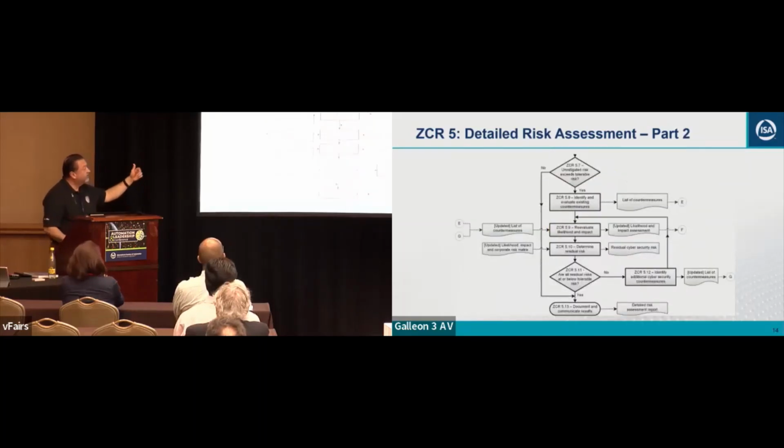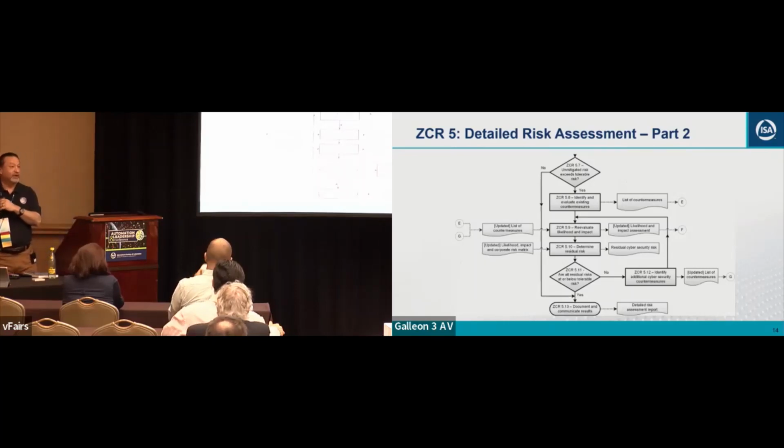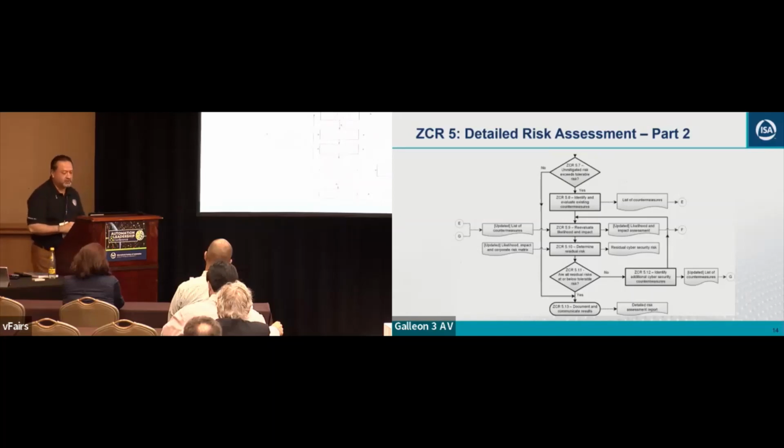And then coming through the rest of the actual assessment is, if there's tolerable risk, can you actually find a way to remediate that? What are some of the recommendations around what you can do to actually lower the impact? And you go through this cycle, right? It's just like a HAZOP, right, or PHA. What if we add another barrier? What if we add another, double block and bleed, right? Same idea here. Maybe we should add some more firewall rules. Maybe we should put a data diode in. All these things come into a risk assessment strategy. But again, subjectivity around not the consequence, but the likelihood and the probabilities. Because a lot of folks try to tie that into your risk matrix, which is fine, but just know there's some subjectivity around that.